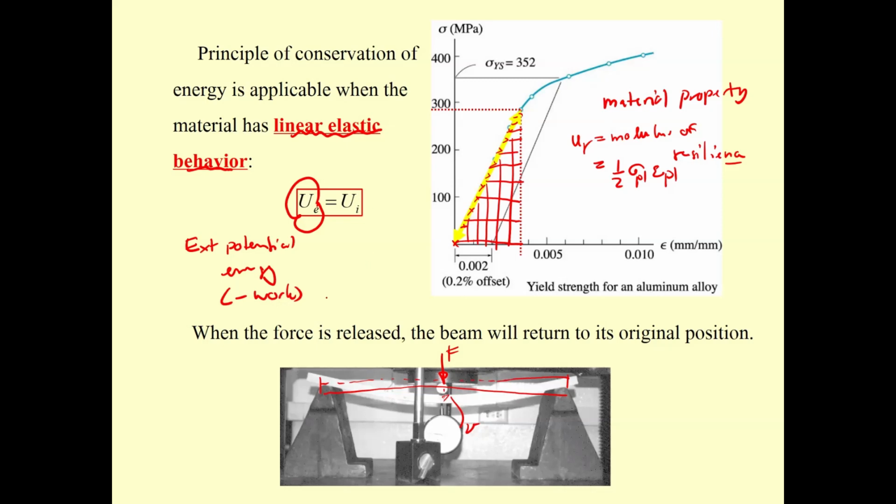Okay, and then this is going to be what? Again, if you do the lab in our material testing, when you test the structure, you have a curve like this one, P and delta. For linear elastic, you get the curve like this one. Then you can plot the curve during linear elastic, and you get the area over here on the structure, and this is going to be the work.